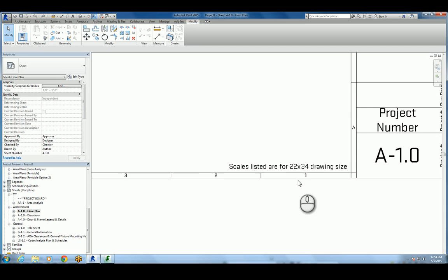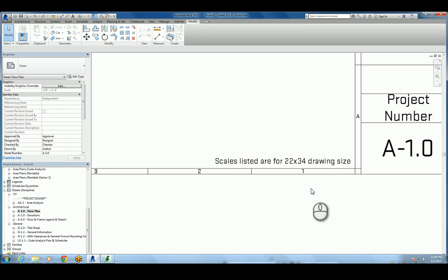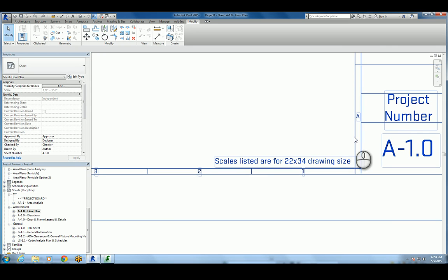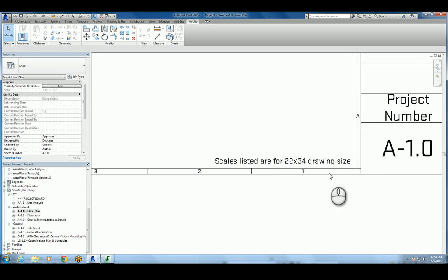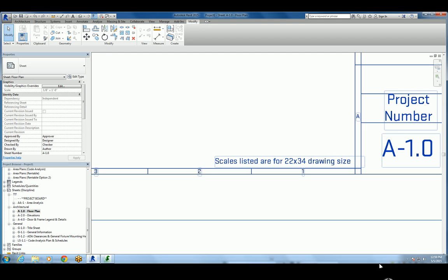So that's in the template right now, so I can transfer this in. So with the view titles, that's what you want to make sure you're doing for your active projects right now: just open up a new project, go back to yours, transfer project standards, just the view titles, and it'll update them because they're all named the same to get that written text in there. And then you'll have to make sure that you bring in the title block, or if you have one that you've already customized for your project, just add this text to the title block.